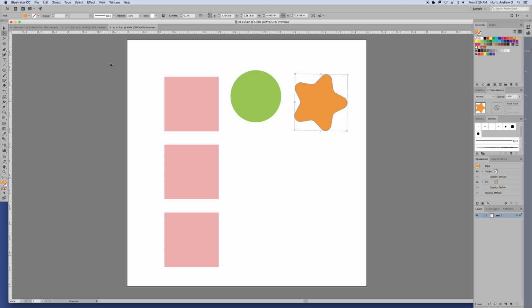If you wanted to pull, show my rulers. If you wanted to make guides, let's say you wanted to have, this is a 1/4 inch, a guide at a 1/4 inch of your document. Basically, all you do is you go into your ruler and you just click and drag, and you'll see once you hit your artboard, this little dotted line shows up, and then you can drop it at a 1/4, and now we have that guide to use that we can snap to. So now we know that that's a 1/4 inch from the edge of your document.